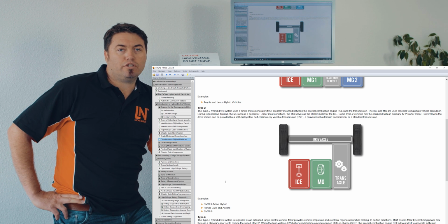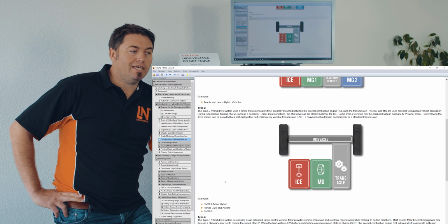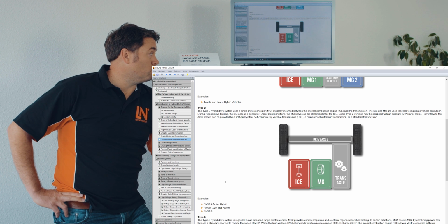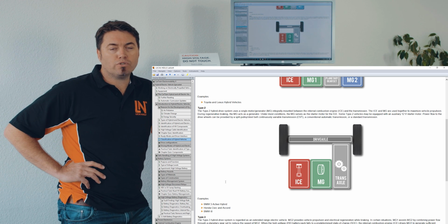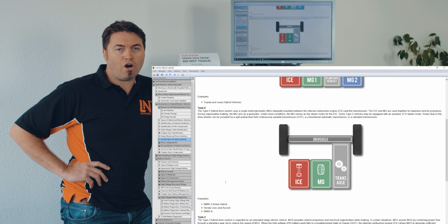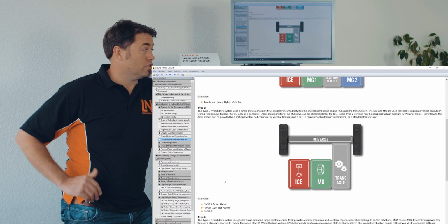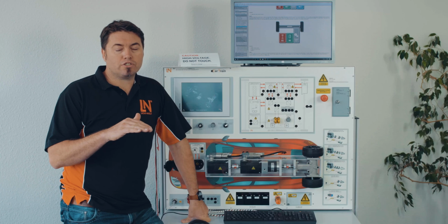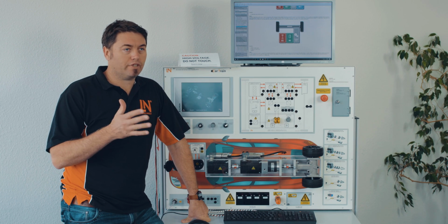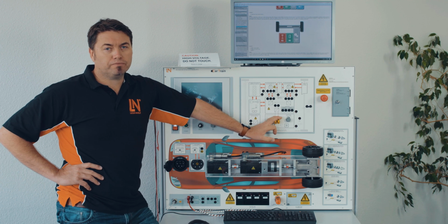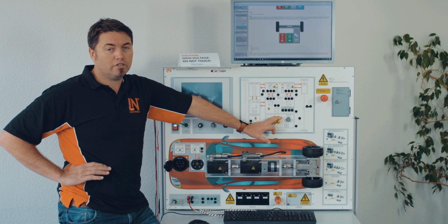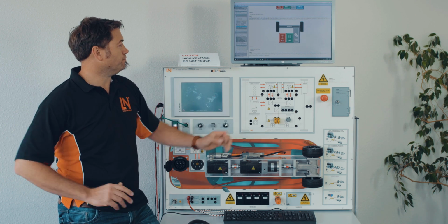The reason they're using 48 volts is, one, it's now looking at a larger 12 volt system, but the threshold for high voltage is 60 volt. So we're staying well under the 60 volt system. So not being high voltage for DC, so we're staying under that, so it's safe.